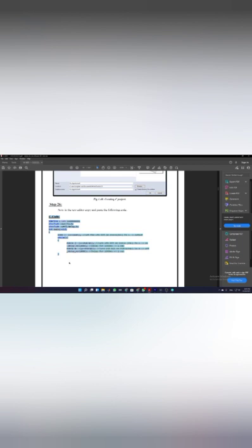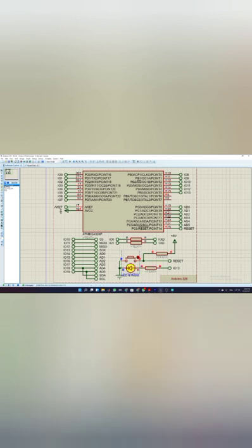Now I'm just going to copy it here, and then you will see that this is the standard file named for the C program. Here you can see that we have included the avr.h. To run this program in Atmel, we have to create the file, and then click on the C++ assembler or C assembler application, and then we'll see that it compiles successfully.